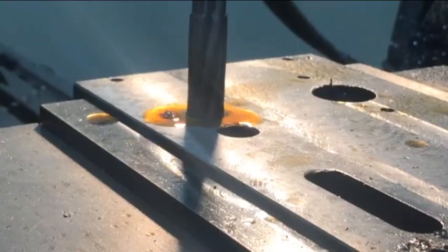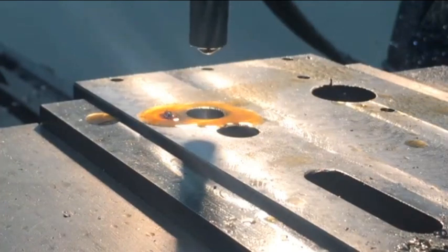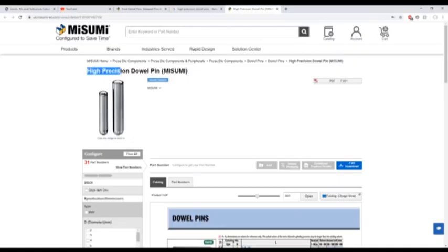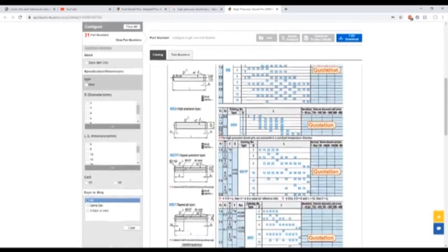Because there will be other smaller pins and your reamer will sometimes cut larger holes, you may also find yourself cutting the largest possible hole for the smallest possible pin. The extra space on top of the allowance is called the clearance. If the clearance is too large, the fit might not work. The only way to change the clearance without changing the allowance is to tighten up your tolerance zones, either by changing your manufacturing methods or buying tighter tolerance pins.